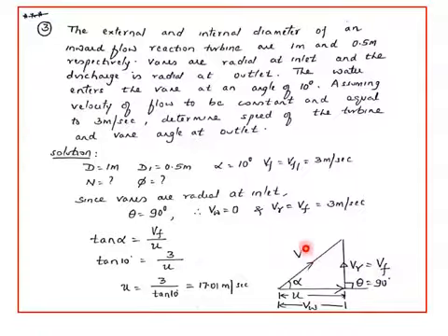Because the component of V in the radial direction is Vf, that has to be equal to Vr. And the horizontal component of V is Vw, so U has to be equal to Vw. This is what you find whenever the vanes are radial. It is only in specific problems where, when vanes are radial, then Vw is 0 and Vr will be equal to Vf. Since Vf is given here, Vr is known. Now you can use this because the angle alpha is given. So tan 10 degrees is Vf, which is 3, and you can find out U. So U can be calculated here.